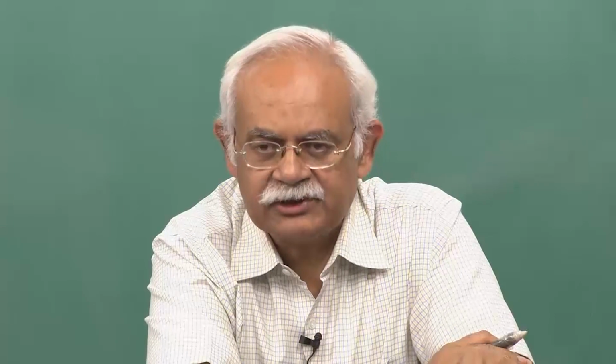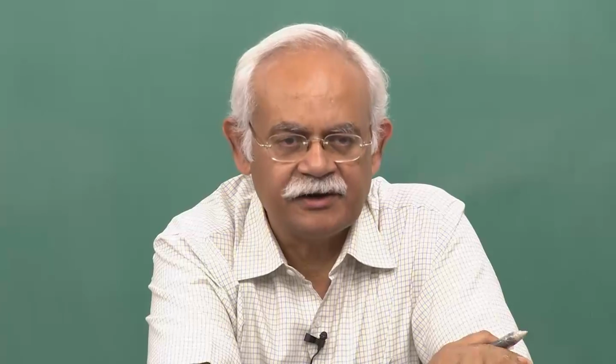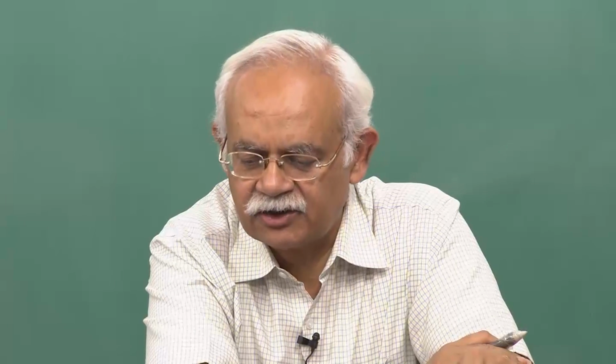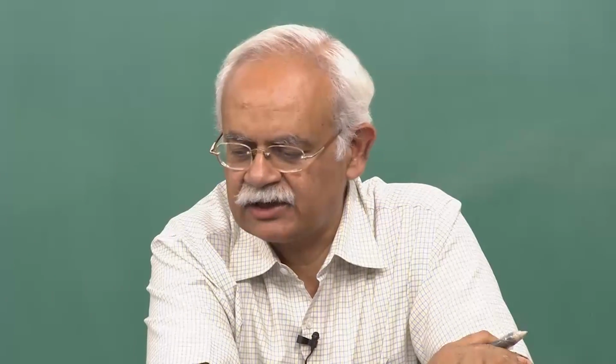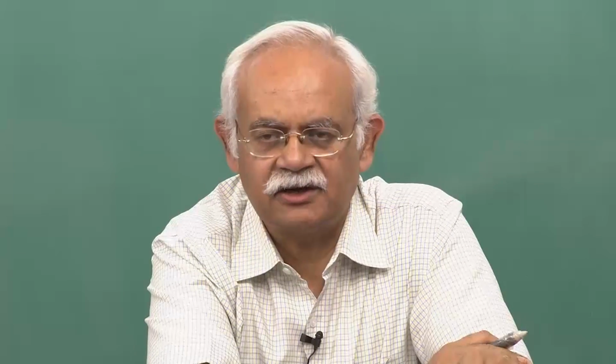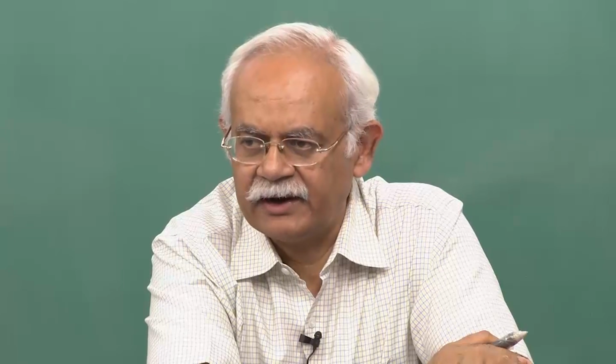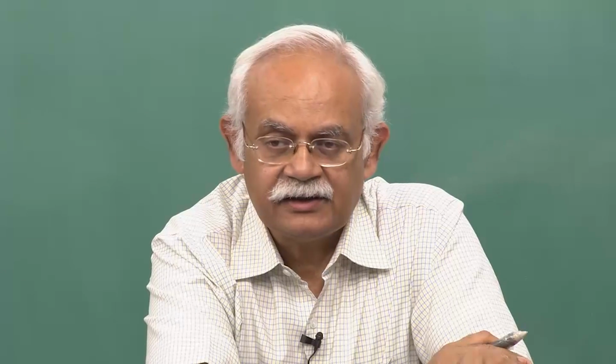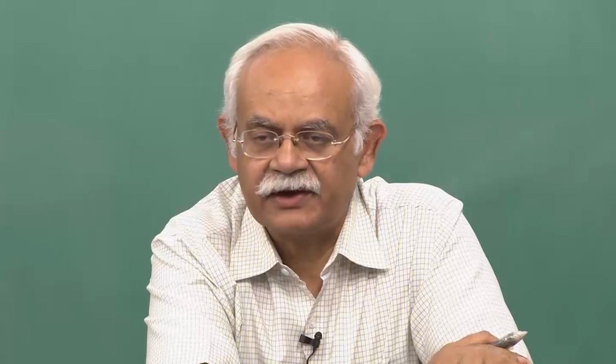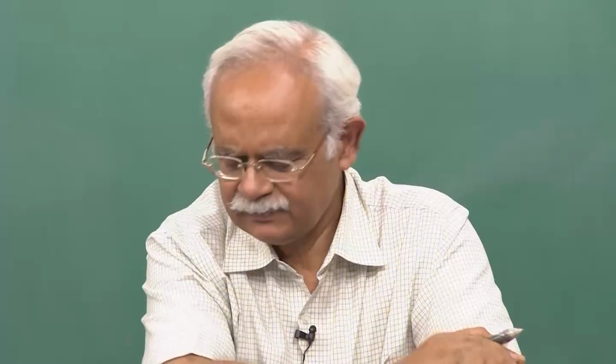We try to make it objective by standardizing different things. We try to standardize the curing conditions, we try to standardize the specimen, we standardize the loading, but then again we must keep at the back of our mind that these are still factors which could affect the determination.